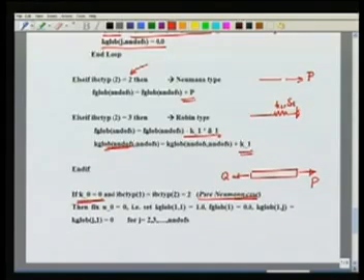In this case, what happens is, if you think of this problem as I have this pen, here is a load here, we are talking of static equilibrium, then what happens? This will remain in static equilibrium, but it can have a rigid body motion, a rigid body mode. This is going to reflect in our calculations. What you will see is that your stiffness matrix is going to be rank deficient by 1. So there is a rank deficiency in the stiffness matrix of 1, and this corresponds to the rigid body mode.